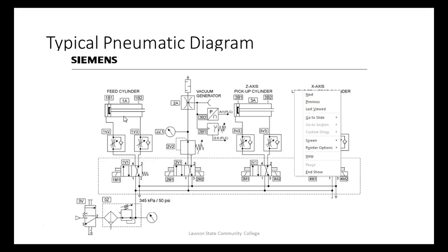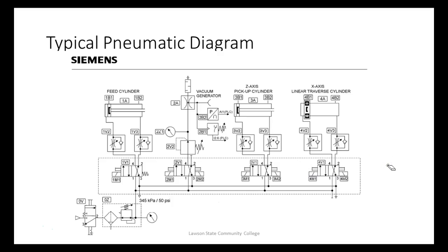So extremely long strokes, then we like to use rodless, but sometimes we can't. You ought to see the cylinders. You used to be able to get down to the locks and dams, this is before 9/11, and you could go down the Warrior River. You could walk right up on them locks and dams and see the big actuators. They had graded floors out there, and you could see the hydraulic actuators that actually open and close that little gate. Those are hydraulic. So we could not use a rodless cylinder to generate that much force.